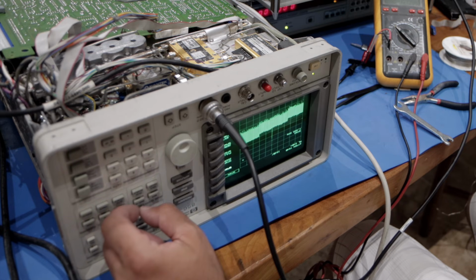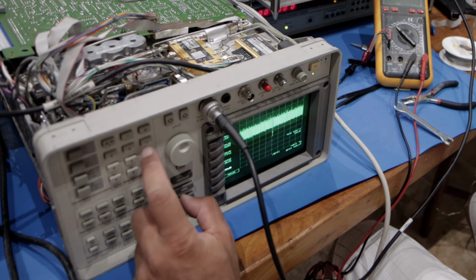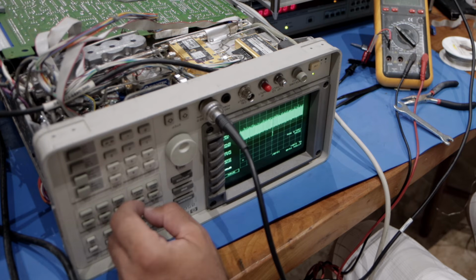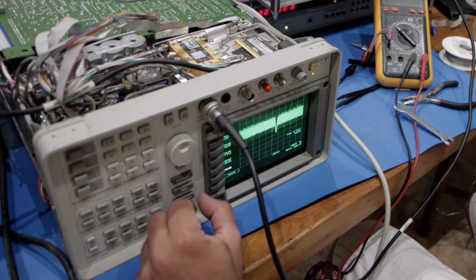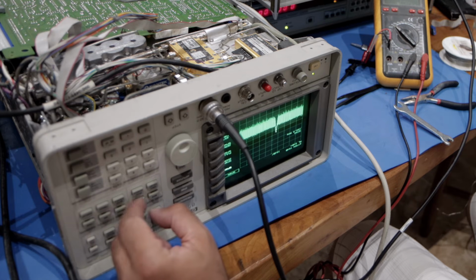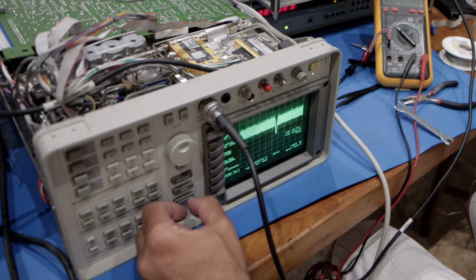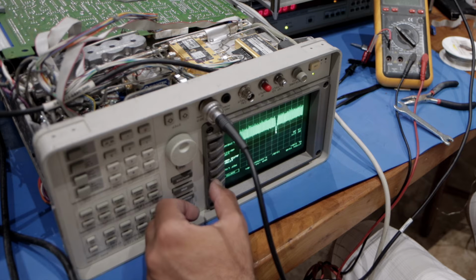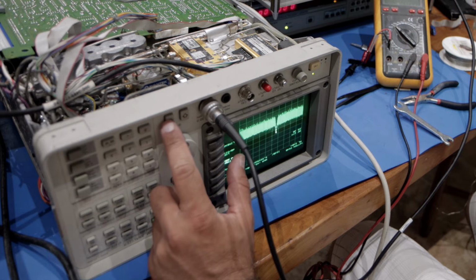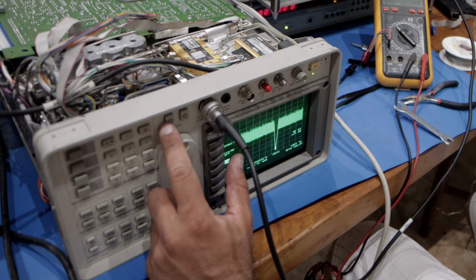Testing it again. Not good. There's a weak signal on the screen now. Earlier, when I tested the 10 GHz signal, it was much stronger. Actually, it turns out the seller, or whoever tried to fix this attenuator before, had left it fixed at 0 dB attenuation, meaning it was basically in full pass-through mode. Now that the solenoids are working, adjusting the attenuation does change the signal strength instead of just the noise floor.